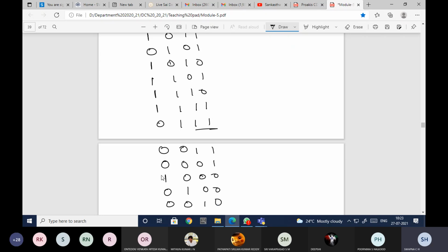So this is how it will proceed. If you observe these C3, C2, C1, C0 values, this is again the repetition. Whatever initial state we had, the same state we are getting one more time: 1, 0, 0, 0. That is the reason. Again it will proceed. One more clock pulse, it will repeat; one more clock pulse, it will repeat. So from this I can say that it is a periodic sequence.